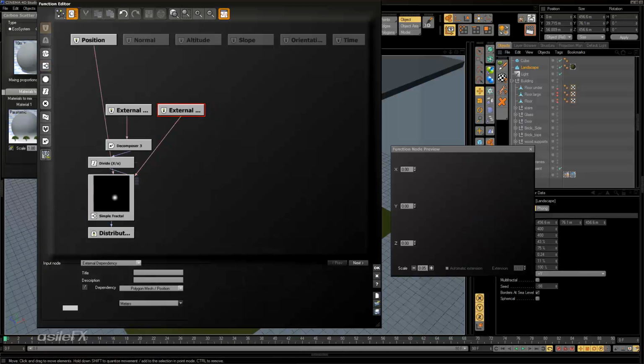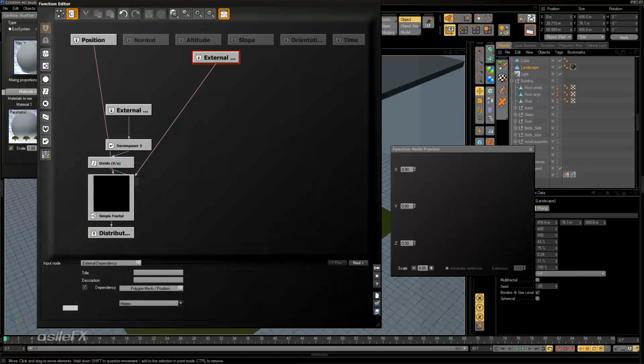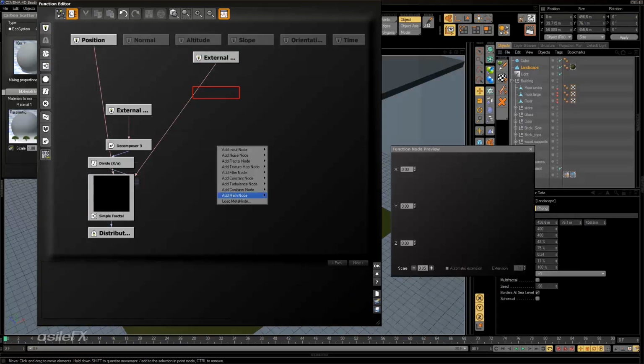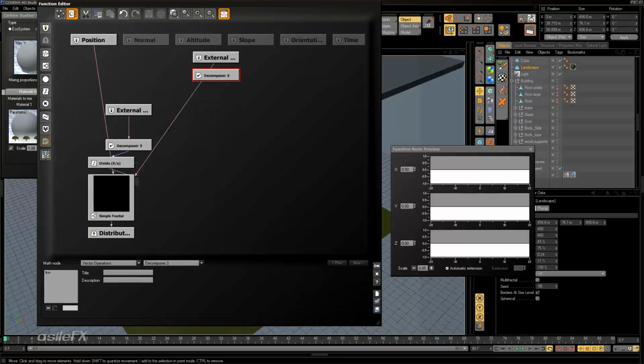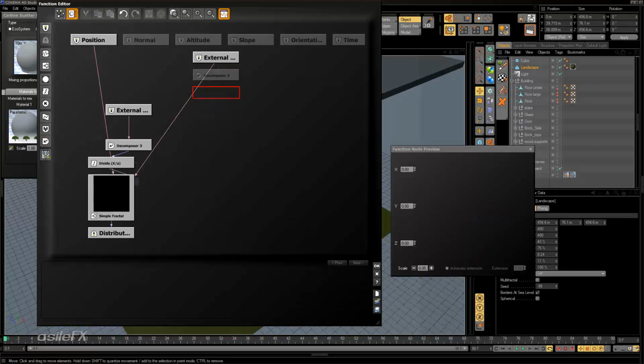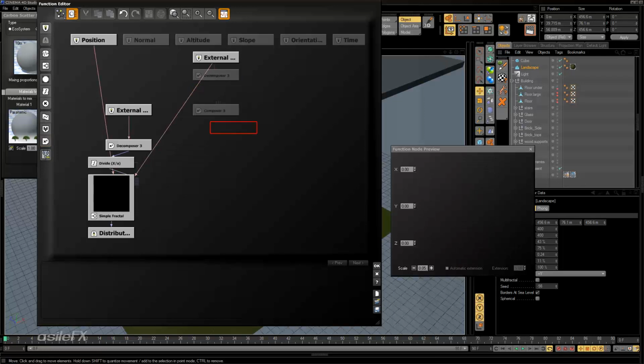Now if you are having issues with setting the wavelength to 0, which can sometimes happen, what you can do is instead just set the origin to 0 and force it to 0 by adding in a MetaNode vector operations decomposer 3, and then we're going to add another MetaNode composer 3. What composer 3 does is the exact opposite of decomposer 3. It takes 3 numeric inputs and converts it to a vector.